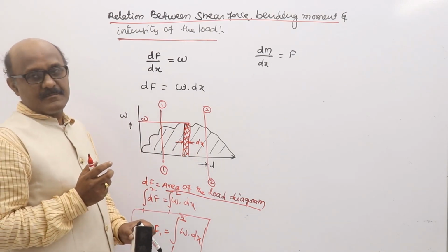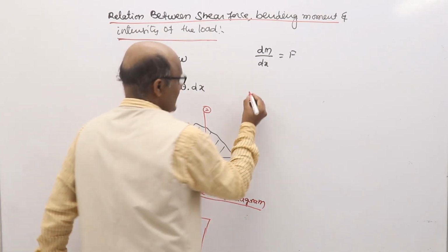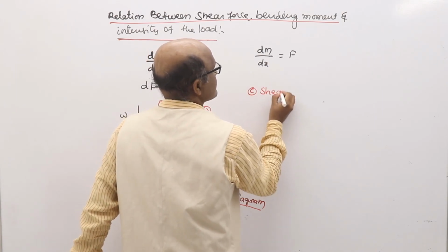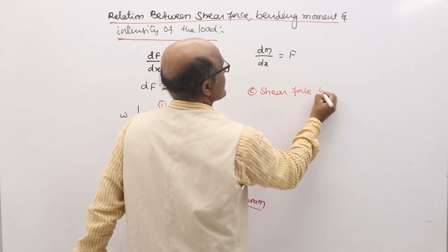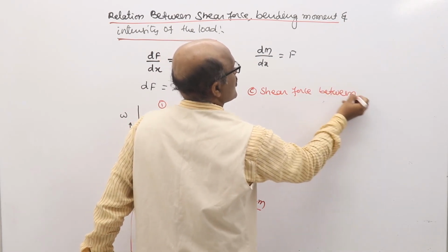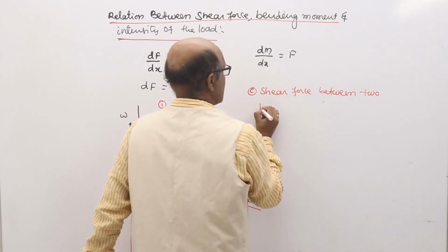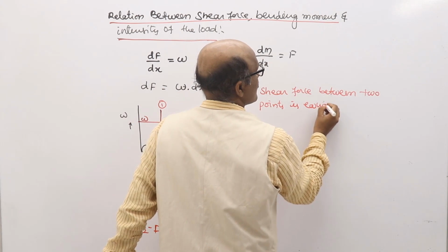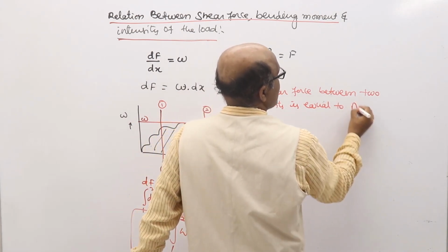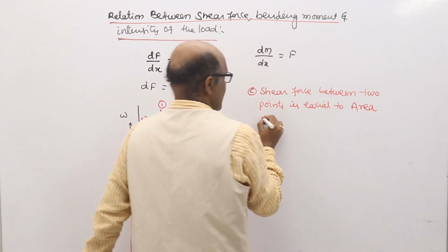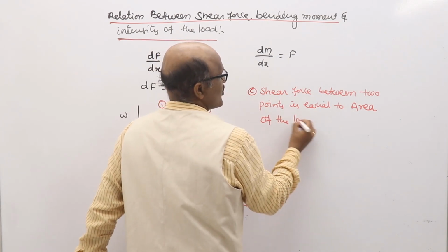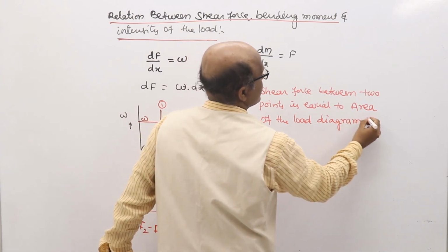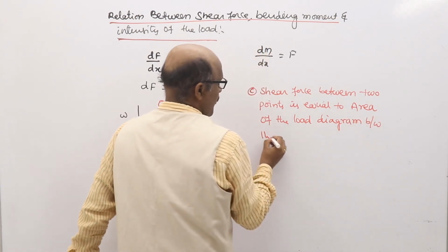So here is the third point, my dear students. The shear force between 2 points is equal to the area of the load diagram between the same points.